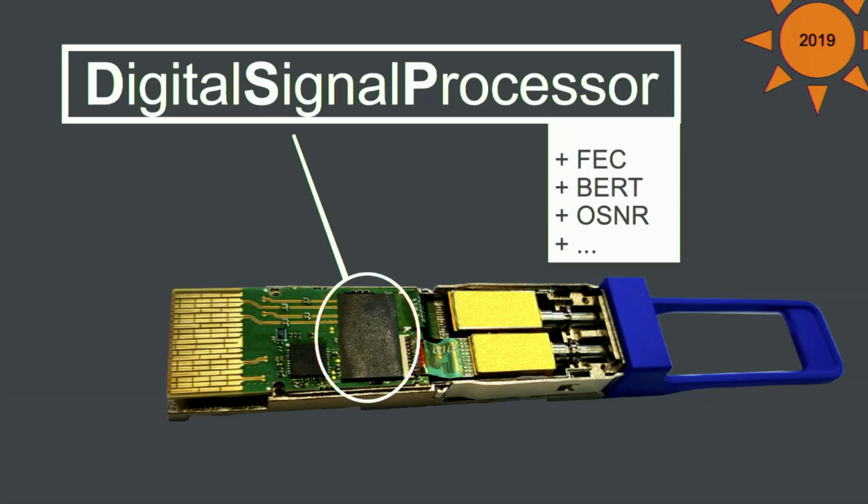So, transceivers, especially coherent ones. We heard a little bit about coherent ones, but we also still have a lot of these classical ones, we call them direct detection transceivers. What is interesting about transceivers nowadays is that just one of these small plugs has a chip on it where it generates the signal.